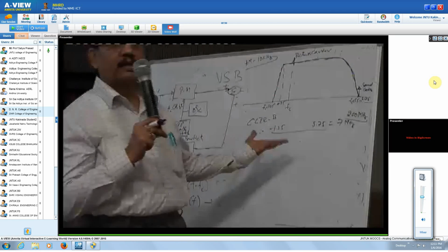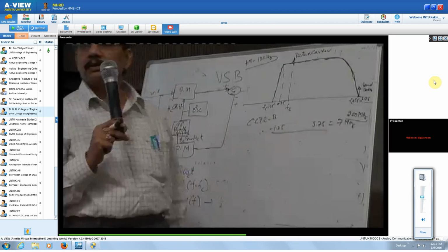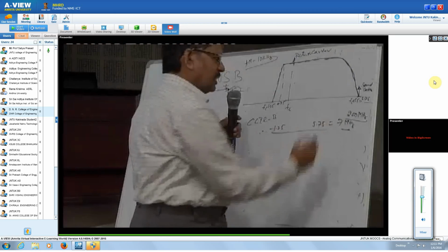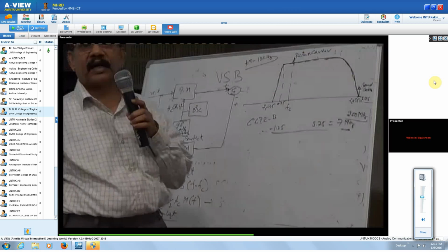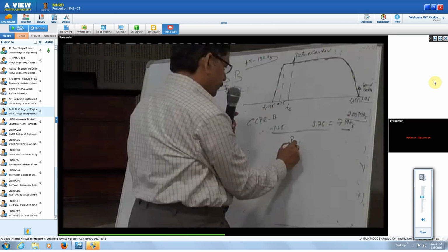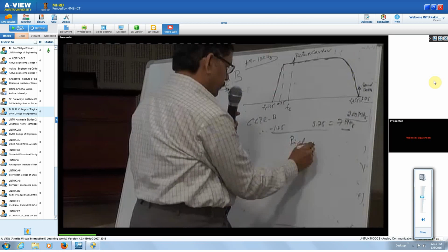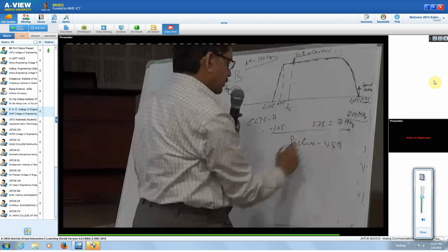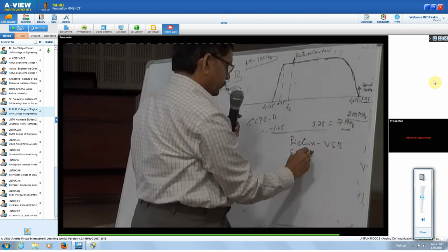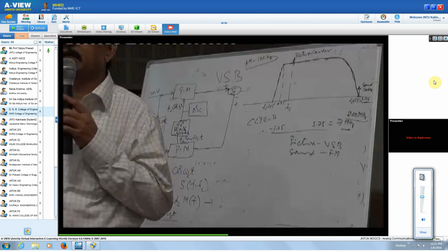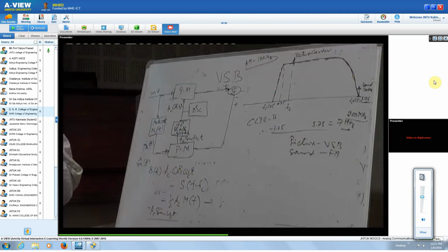If you use AM, then we require 10 megahertz, whereas with VSB, we are having only 7 megahertz. So the picture modulation is VSB or AM, whereas your sound will be going for frequency modulation.